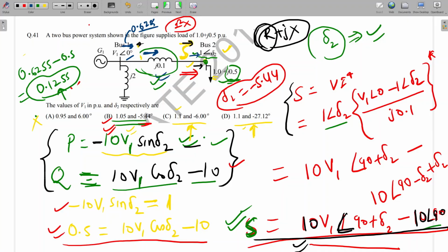Sir, suppose we have a leading load, then power cannot flow to the load? See, you are telling in terms of load; I am telling in terms of bus. A bus means a power system bus where we maintain some voltage and some angle. So this is the power flow equation between two buses, not between source and load. Whatever the load is, either leading or lagging, it will draw real power. Is it clear?